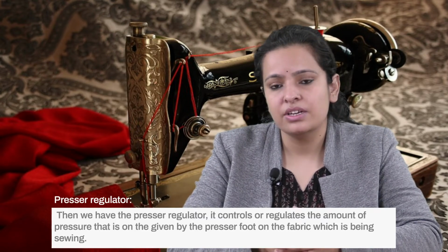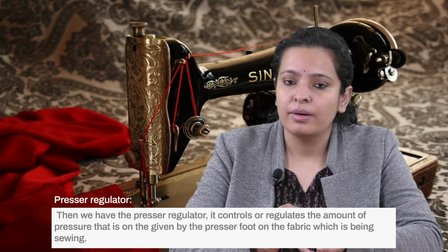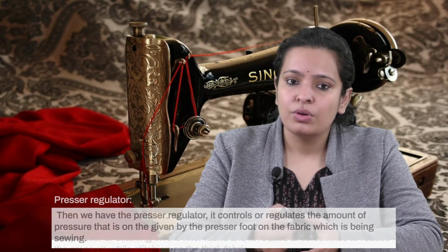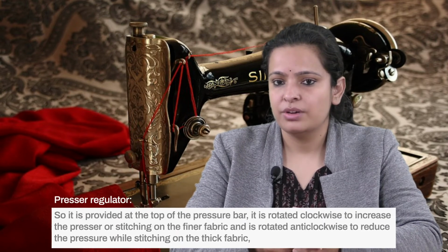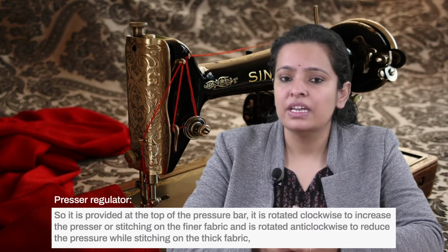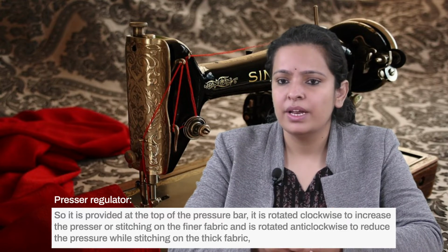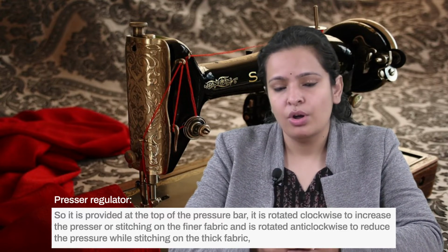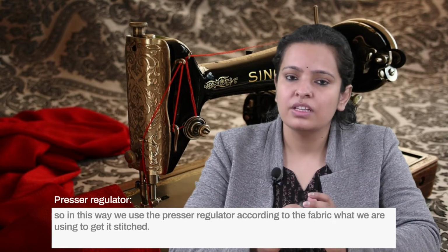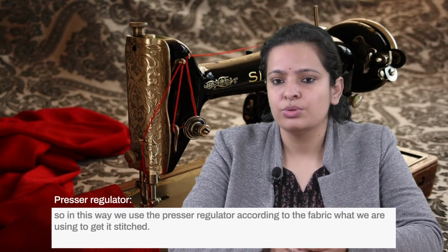Pressure regulator controls or regulates the amount of pressure given by the pressure foot on the fabric which is being sewn. It is provided at the top of the pressure bar. It is rotated clockwise to increase the pressure for stitching on finer fabric, and is rotated anti-clockwise to reduce the pressure while stitching on thick fabric. In this way we use the pressure regulator according to the fabric we are using to get it stitched.